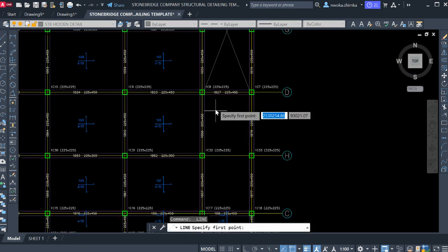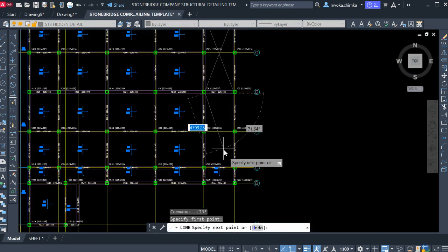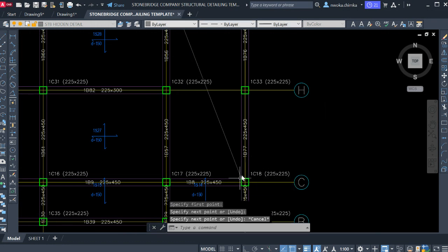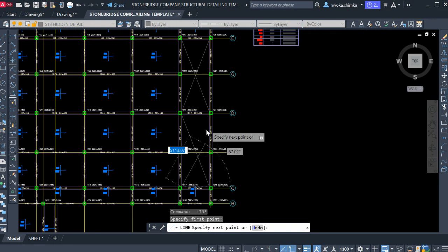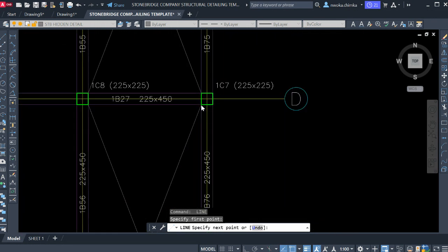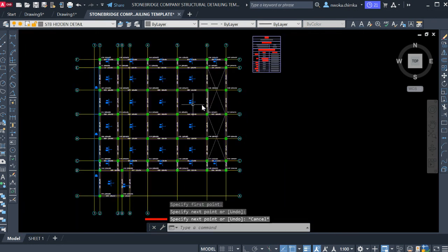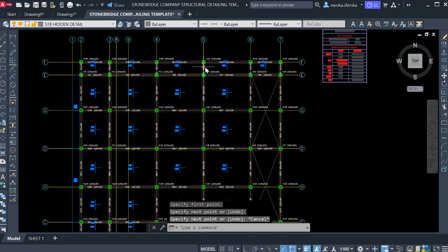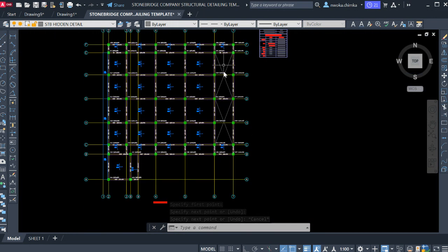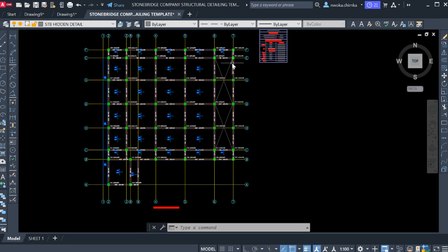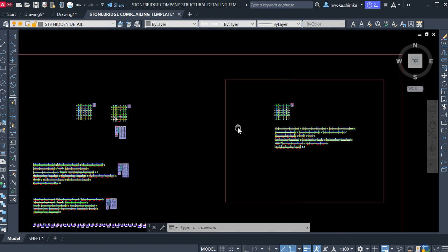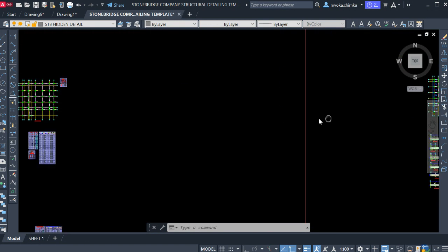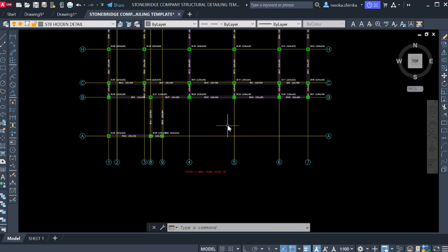And then also we click on this again because this staircase is like a two-way staircase. They have staircase in that direction and also a staircase in this direction. So right now I have identified my staircase so that when we'll be doing the slab detailing for this floor, we will not mistakenly put in slab on this staircase area. So right now, this is the only void that we have on this structure. And mind you, this is a two-story building. As you all know, we have the story one and also we have story two and then the roof beam.